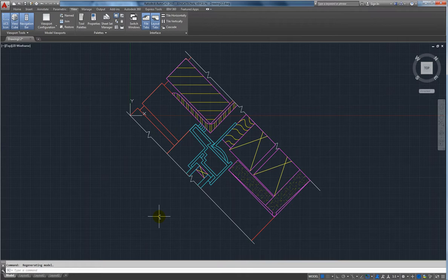So in this case, you're saying, no, John, you rotated the drawing. No, I didn't rotate the drawing. I rotated the UCS. But because we're looking from a top UCS view, you can see east is still east, north is still north. All right? We haven't rotated our world. We just rotated our UCS. So I just took my desk and turned it. Okay? When you go in your room and turn your desk, the universe doesn't rotate with it, right? Your desk rotates, the universe stays still. So that's what's happening here. We're just rotating our desk. Is that simple? Does that make sense?